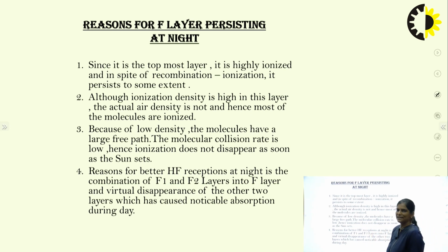So the reason for better high frequency reception at night is the combination of the F1 and F2 layers into the F layer, and the virtual disappearance of the other two layers, which caused noticeable absorption during the day.